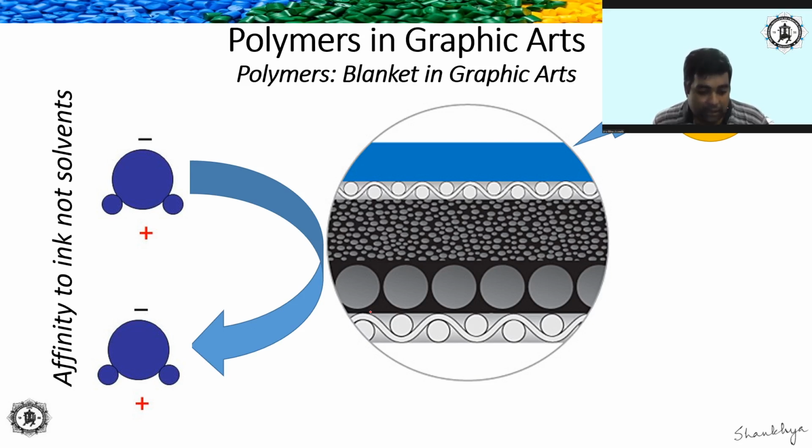Other materials like ketones and turpentines also cause the blanket to swell. Benzene and carbon disulfide dissolve rubber. They try to swell the blanket. So whenever you choose a solvent to be used for cleaning a blanket, you should be well aware of the constituents of the particular material, and you should avoid these ketonic solvents and aromatic solvents. This will ultimately reduce the lifespan of the blanket, and it will reduce the quality of printing as well.